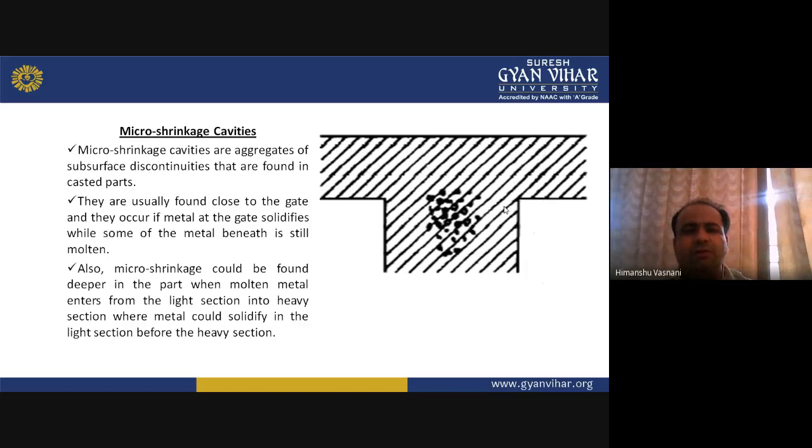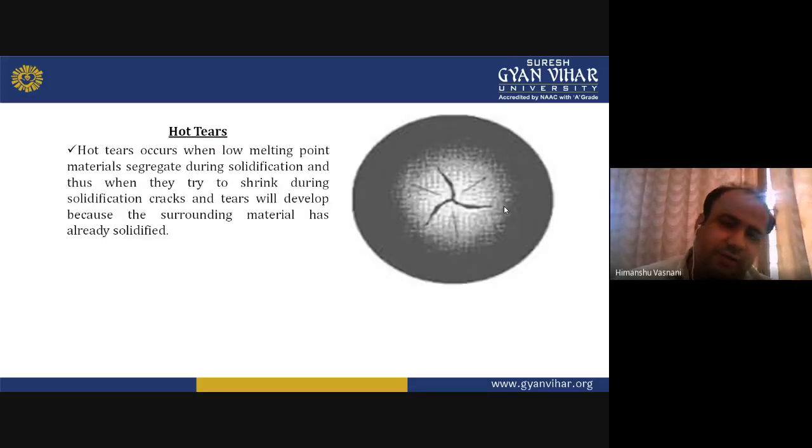Normally they are found at the bottom beneath the molten material, because where will they go? It shrinked earlier so it will automatically assemble at the bottom. Overall this will create a discontinuity which will affect the surface of the workpiece prepared. So this is also not acceptable.